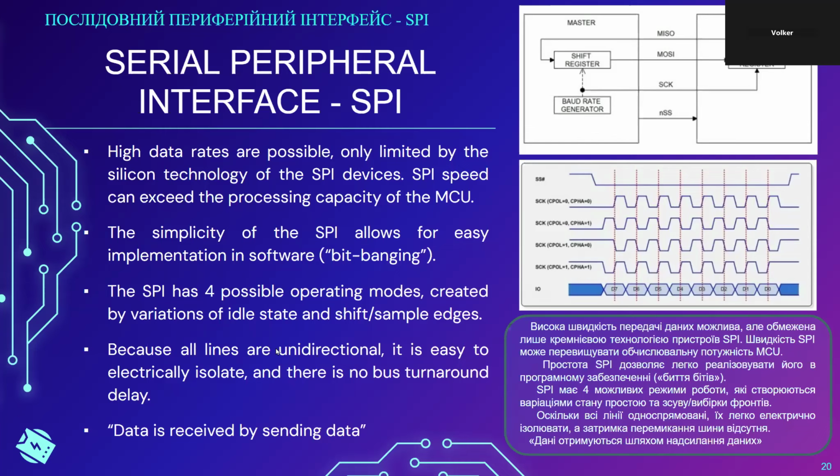And generally, these pins are capable of supporting a number of different devices. So what sometimes can happen is that all the important devices use up pins that otherwise are being used by an SPI interface that is on the chip, the actual SPI interface that is supported by the microcontroller. But the pins are used up. You're using them for other purposes.